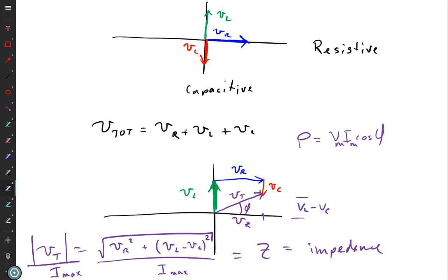So you don't want to have that phase angle 90 degrees because you're charged for power you're not using. What do you want the phase angle to be? 0 degrees. So you're using the power you're charged for. Because you're charged for voltage times current, and you want what you're using to be as close to that voltage times current as possible.